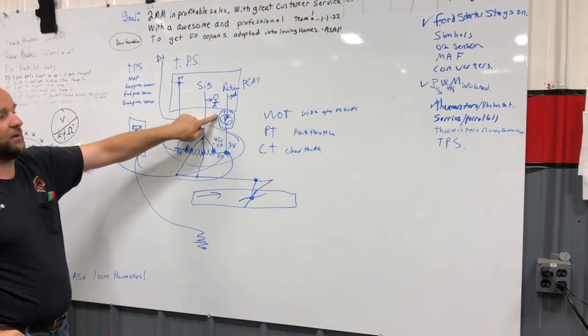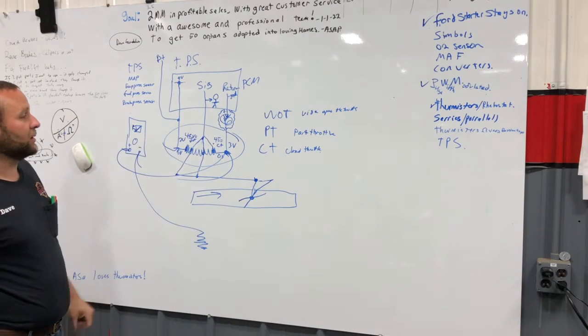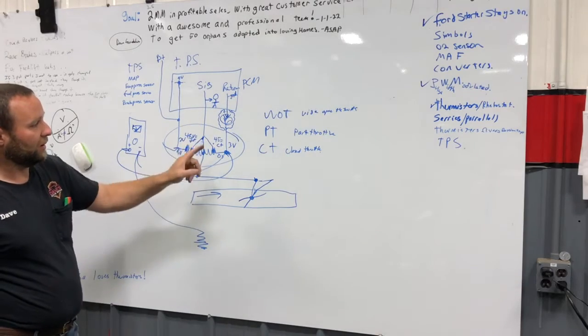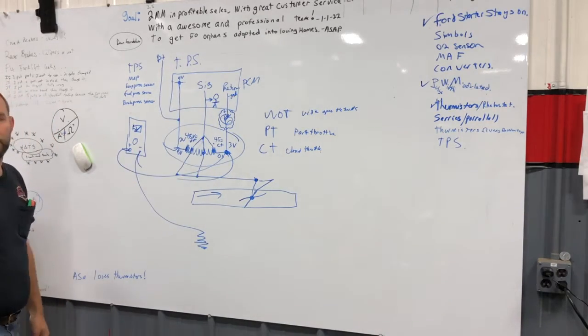This became a resistor instead of a ground wire. Does that make sense? Yes. So how you check that is you go from ground to there, and if you have voltage, you know that you have a bad wire farther up your system.